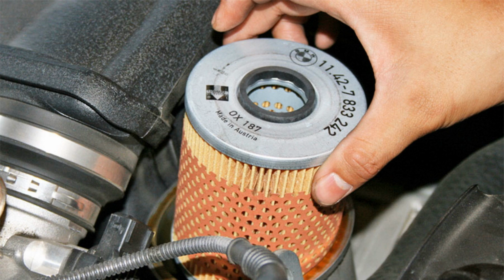Note that the volume, capacity of the engine lubrication system of an average passenger car lies within the range of 3 to 6 liters. This is the place where the technical fluid is cleaned from the debris that inevitably appears on the rubbing surfaces as a result of intensive work and ingress from the outside. We have already mentioned microscopic metal shavings. Other contaminants can be soot and carbon deposits formed during combustion of fuel-air mixture, dust, and even dirt particles. The oil filter traps all of this, gradually clogging, resulting in poor filtration.